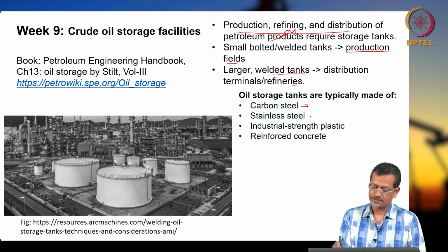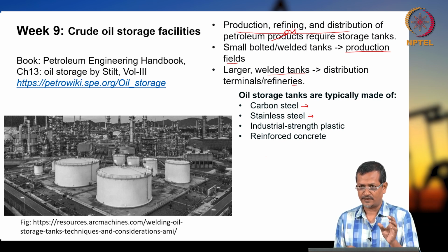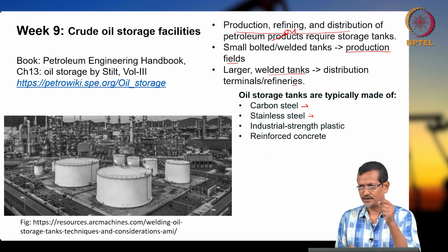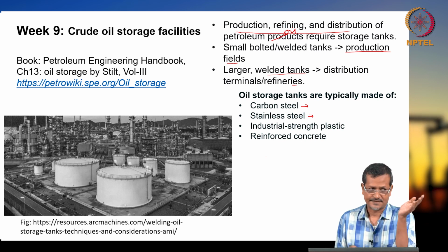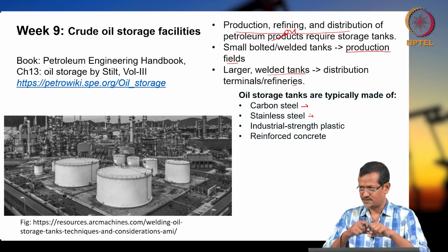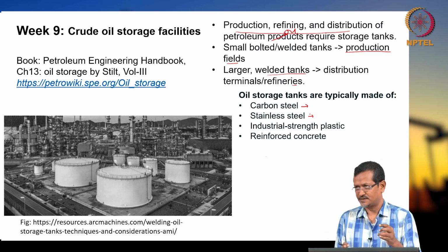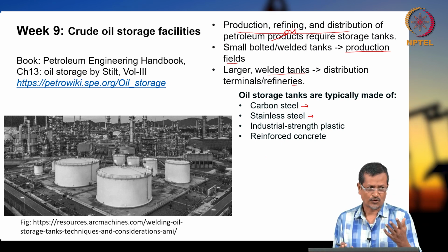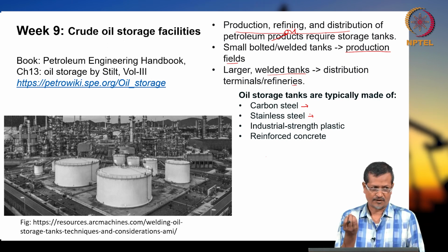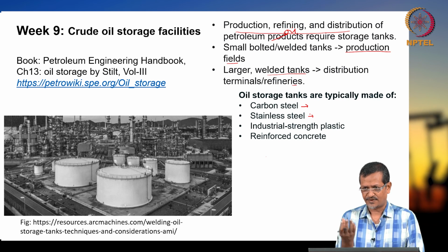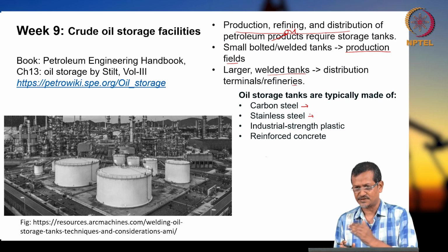When I talk about steel and carbon steel, I think you may have an idea from material science. Pure iron is very corrosive. If you add a small amount of carbon content, like 0.5%, you create mild steel. Mild steel is very easy to manufacture, ductile, and malleable. But if you manufacture your pipeline system or surface production systems using mild steel, it will be very corrosive, which is dangerous for your system. It gives contamination of iron oxide, and leakage and fracturing are possible. So we should not use mild steel. We have to go towards stainless steel or carbon steel.